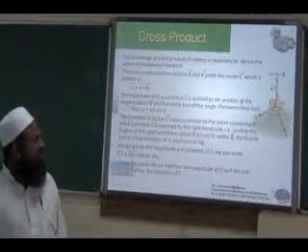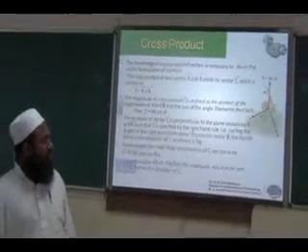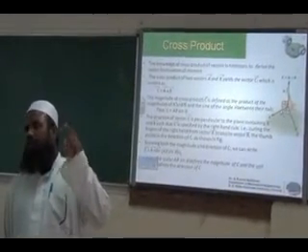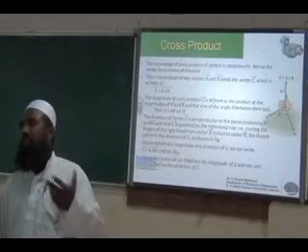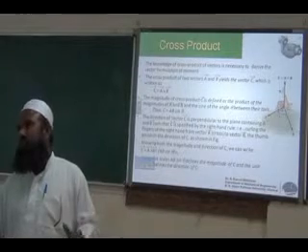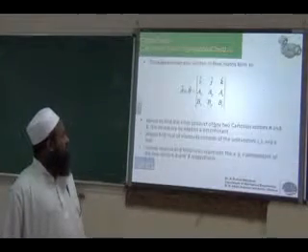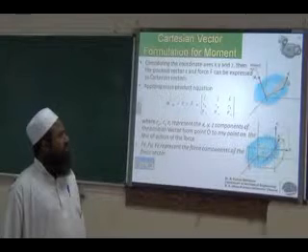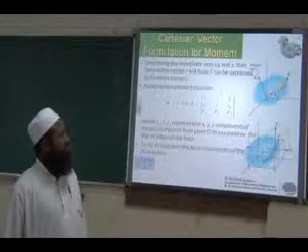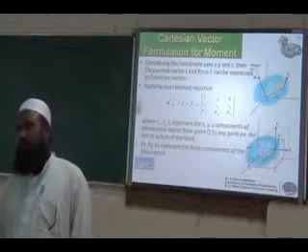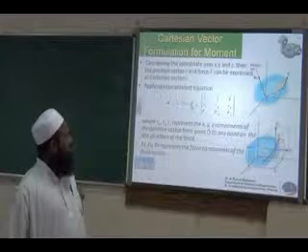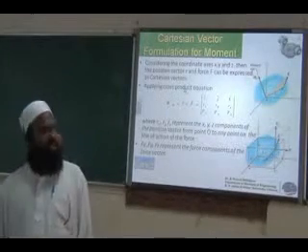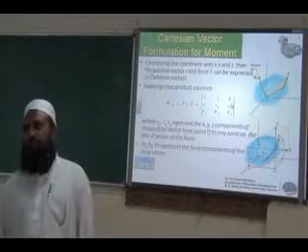So if you consider the force and its distance from O, the position vector and force vector, the cross product of position vector and force vector will produce another vector which is called the moment. So we use the cross product approach to represent moment. This is the Cartesian vector form. R cross F, the position vector R cross the force vector, will give you the moment M naught, the moment about O. So it can be represented in the matrix form for Cartesian vector.